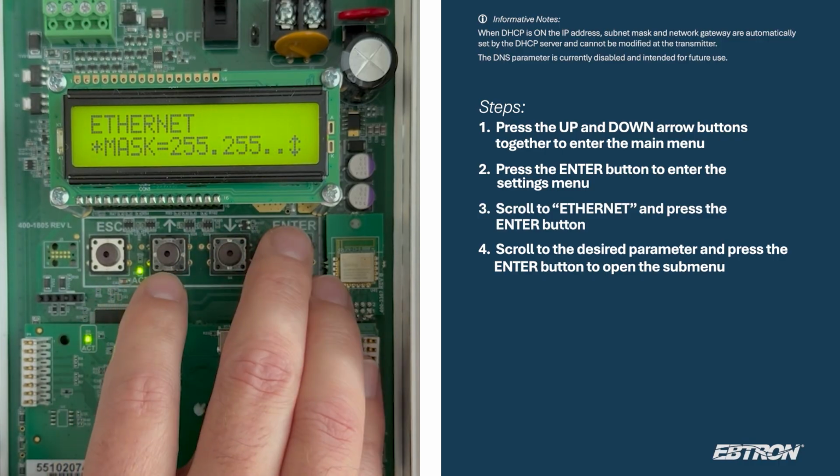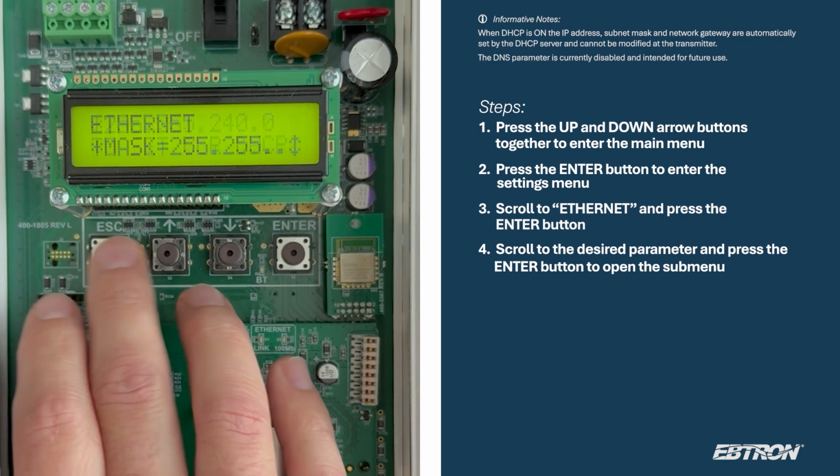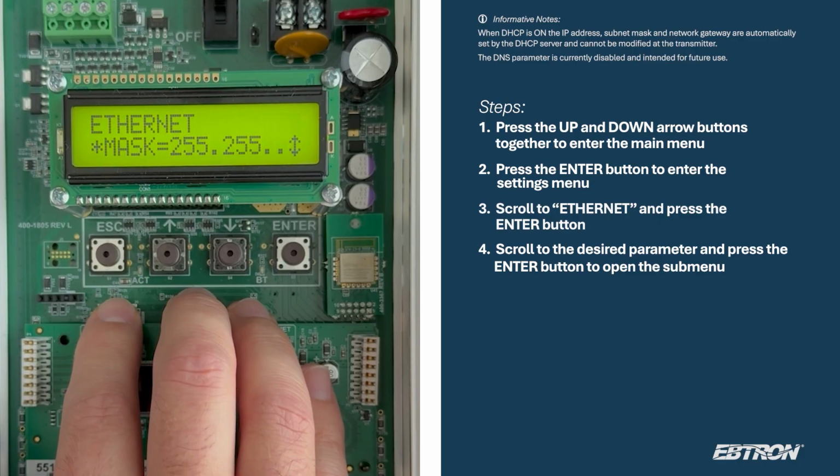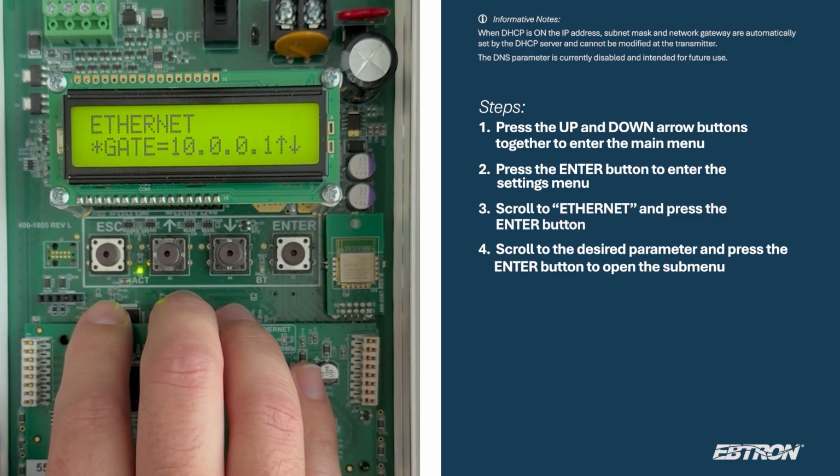Subnet mask. The subnet mask defines the network's addressing range. The default is 255.255.240.0, though this may vary depending on your network configuration. Like the IP address, the subnet mask can only be changed when DHCP is off. Network gateway. This is the IP address of the default network gateway used for routing data between the transmitter and devices on other subnets. The default gateway is 10.0.0.1, and it can only be adjusted when DHCP is off.